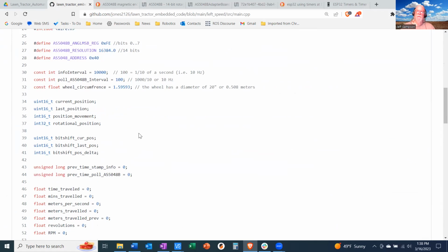But back to your original question, no, you can't do that. Because the chip internally takes the two magnetic fields and does all kinds of math on it and generates a number between 0 and 4095, or 0 and 16384, or whatever the resolution is. Somehow you have to read that number out, and hooking up a simple interrupt is not going to do that. You've got two communication interfaces you can use. You can use the I2C to read out the value, or you can use the SPI to read out the value.